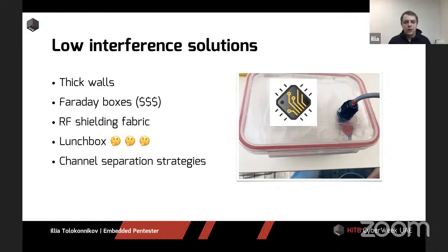If you don't have this kind of separate rooms, or you run out of them, there are a couple of options. One of those is Faraday boxes, just a mid-sized box, about 0.5 meter in each dimension, radio frequency isolated. They have power pass-through, so they have wall sockets inside the box. They have network pass-through, so you can connect your wireless router via Ethernet or something like that. The problem with those is they cost a lot. On average, a couple of $1,000 US, maybe even more, but they're really cool. We have several of those, 3 or 4, I believe. They're occupied 24/7 with different tests, and it's hard to get our hands on one if you really need one in a pinch.